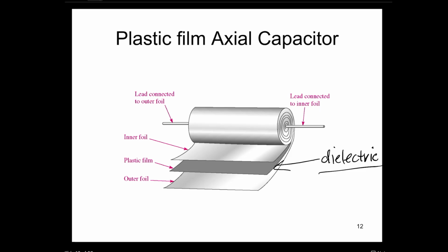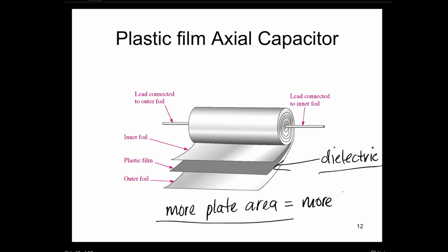Now, when it comes to electrolytic capacitors, like I was talking about, they're generally built like this. So when they blew up in the lab years back, when I was telling you about that, you would actually see all these layers in an exploded view, literally an exploded view, and all the stuffing and the dielectric and everything would all explode out of it. But I think you kind of get the idea. The idea is that giving you more plate area is significant here. More plate area is actually going to give us more farads, more capacitance.